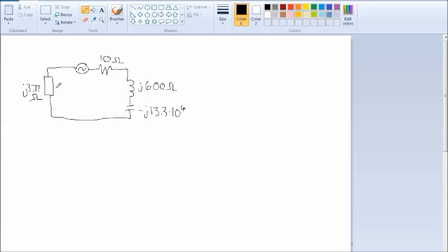So I combined those two elements, and remember, whenever you have two parallel impedances, it's product over sum. So you take the impedance of both of them, multiply them, and then divide by their sum. Remember, the impedance of the capacitor was 1 over j omega c. The impedance of the inductor is j omega l. So I would recommend you do the same mathematics to simplify the circuit and see if you get the same answer as I did right here. And I will show you right now the work that I did.